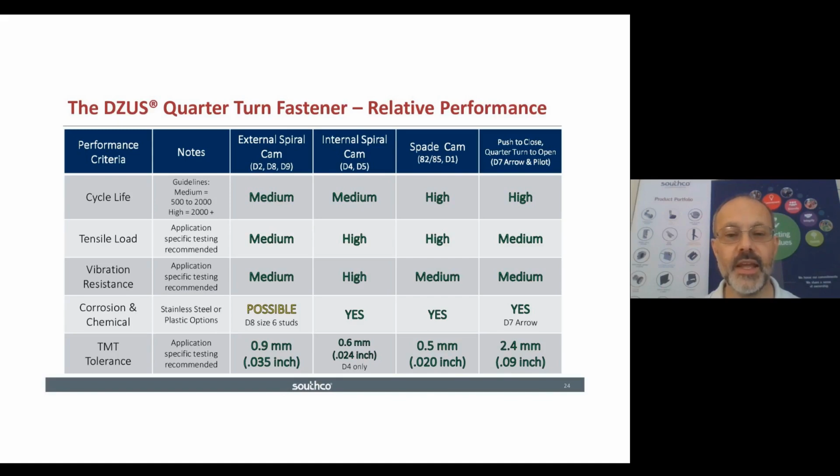That's to say it does allow a small amount of movement in and out from the panel fastening direction where vibration can occur. It won't come undone, it remains secure, but there is some free movement possible under vibration. And this particular section of the table is indicating how well the fastener will limit the vibration of the panel under that vibration load.